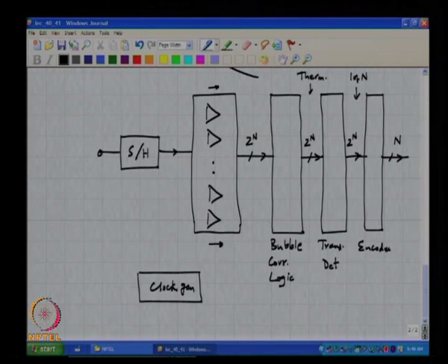clocks. And for example, as we have already seen long ago, the sample and hold needs non-overlapping clocks and perhaps boosted ones and so on. So you can't expect all those myriad clocks to be given to you from the outside. All you will get is a single master clock, and from this single clock you have to generate all the other clock waveforms that you need, right. So this will go to various places on the chip.